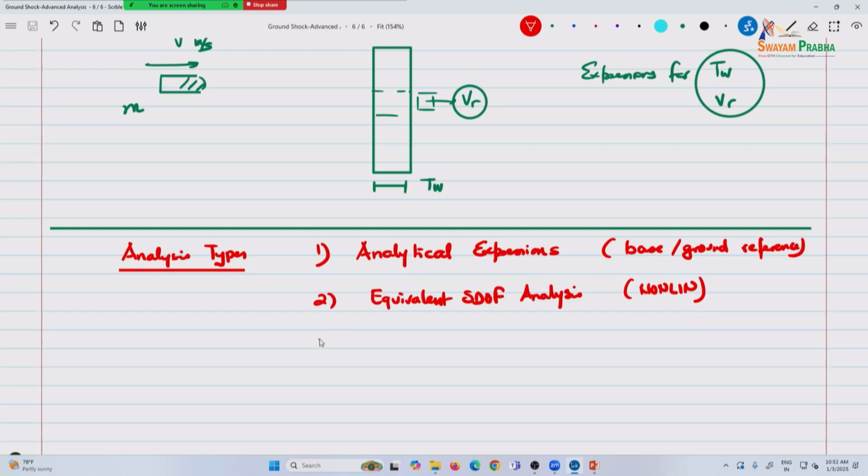And then the third thing is, even yesterday I was having a discussion with somebody, and for that also, equivalent SDOF analysis, all you have to do is, foundations on springs, for example. You may not have an equivalent equation. Let's say you know delta is equal to PL cubed by 48 EI, so your K is equal to 48 EI by L cubed. So, you have analytical expressions for it.